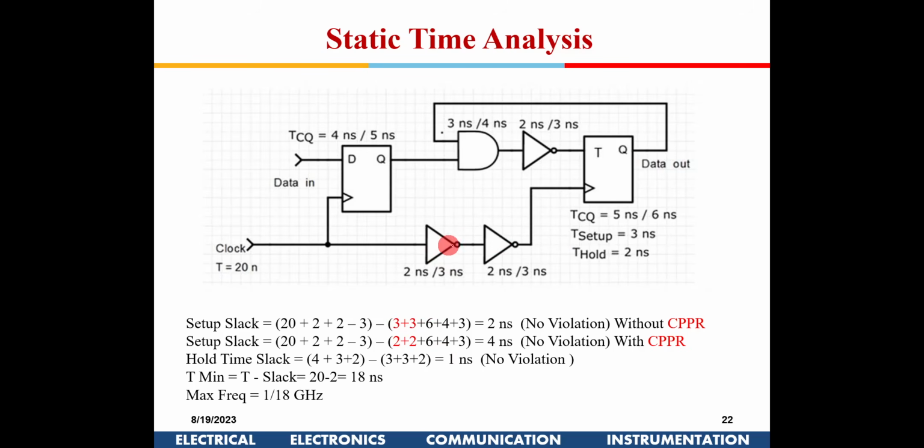So whatever is the common blocks which are there in the data. So this is another example with the feedback. Okay, so not necessarily the launch path and the capture path have to be different. In this example we see this is the launch path and this is only the capture path, capture flop also, because the same data has to come from here to here. So this delay is more out here.